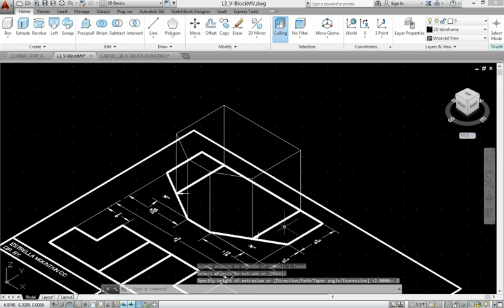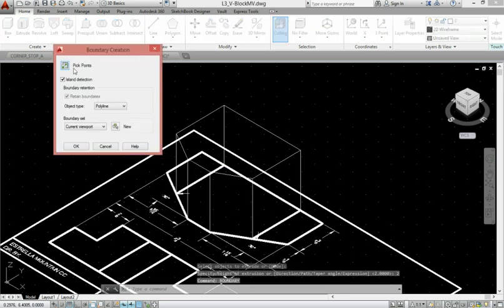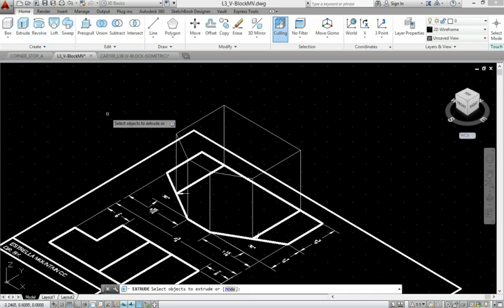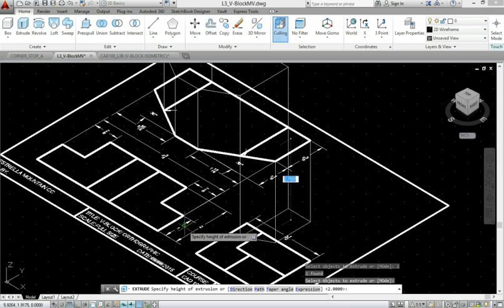Now make a boundary on either end and repeat the process. Boundary on this side. Created one there. I'll extrude that. Notice I'm typing in L, enter, to pick the last thing I picked, and then enter again. Point up, and the height of this feature, in case you forgot, it's right there, it's 1.